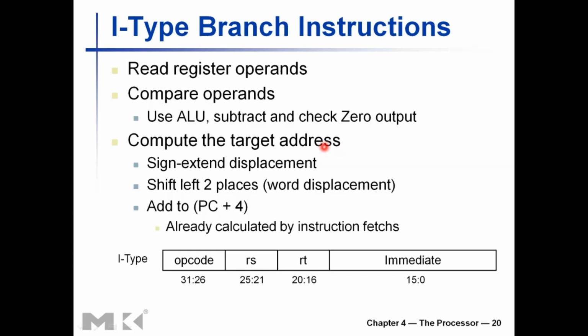So when computing the target address, we have a 32-bit value in the program counter and a 16-bit immediate value, which we need to add on top of the current program counter value. The immediate value here tells how many instructions you need to jump ahead. The 16-bit immediate value in the instruction indicates whether you need to jump 5 instructions ahead or 10 instructions ahead or 10 instructions behind compared to the current PC value, the next instruction to be executed.